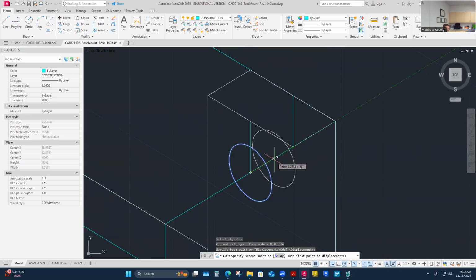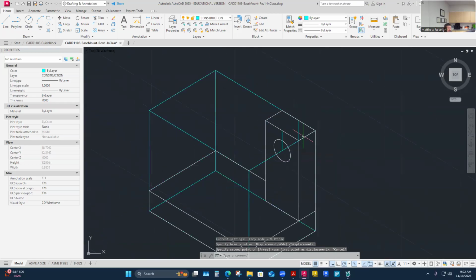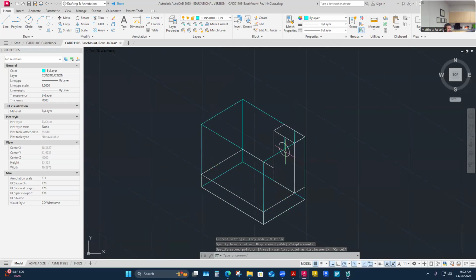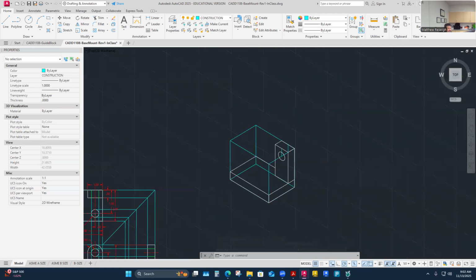And we experienced that on some of our parts that we had to do auxiliary views for on our orthographic projections. It's the same concept. Just keep track of the entrances and exits of these features, and if they need to show through, then let them. So here I'm just doing a double check that at this particular projection angle, you're not going to see any of the exit hole. So I can just eliminate it. I don't need to put it in there. This is going to be sufficient to carry the information. But just watch yourself, just check yourself.